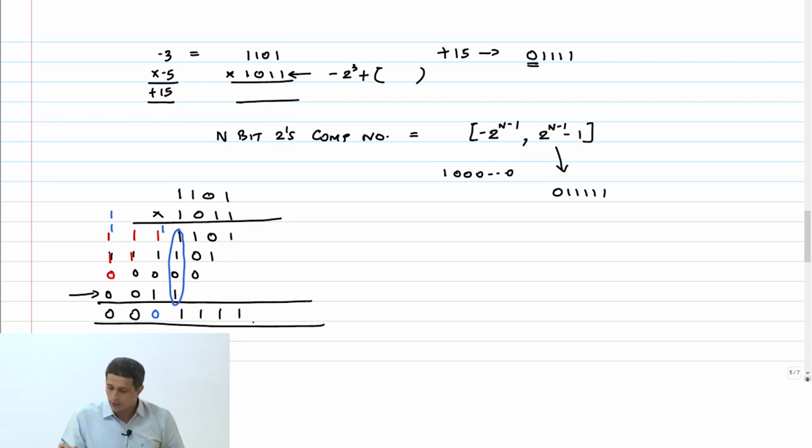You get it? So now, for example, here, if I sign extended this further, right, 0 and then put another 0 here, then this carry would still do the same thing, will give me 4 ones, 2 ones, get me all zeros there. This is a very subtle point. Go back, look at the arithmetic that we did here, the mistake that we made earlier. The carry cannot be dropped, or the carry is not the MSB of your 2's complement multiplication. The carry is going to enable sign extension to as many bits as you want.